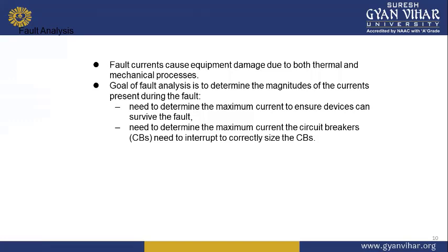The fault current causes equipment damage due to both thermal and mechanical processes. The goal of fault analysis is to determine the magnitudes of the current present during a fault, and to determine the maximum current to ensure devices can survive the fault.